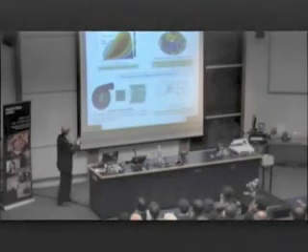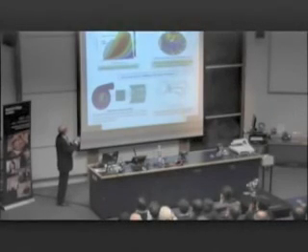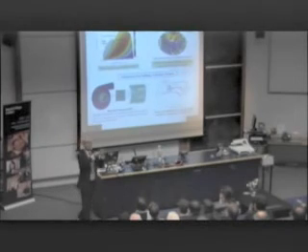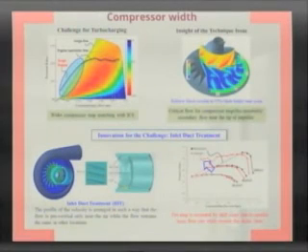And a compressor has a peculiarity that in some area of its map, pressure against mass flow, it moves into a region called surge, into which you don't want to move. It's bad news. And therefore, you might want to move. Your black line is your desire as a designer.